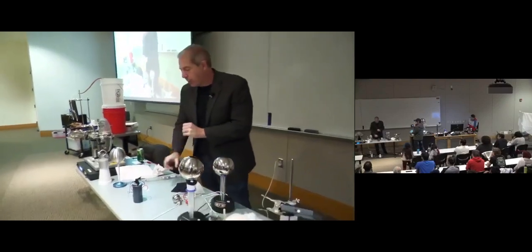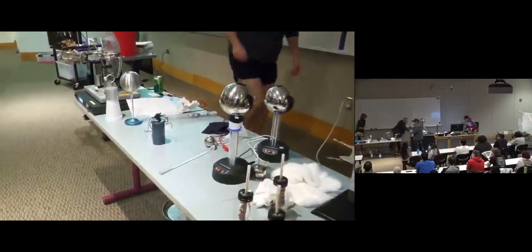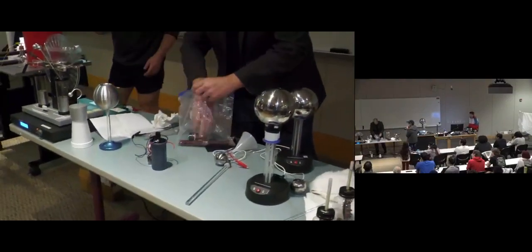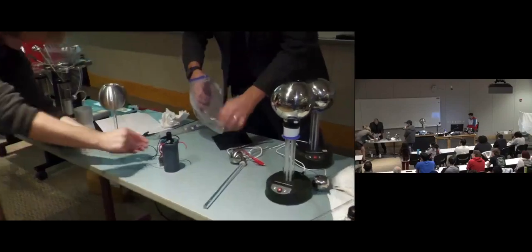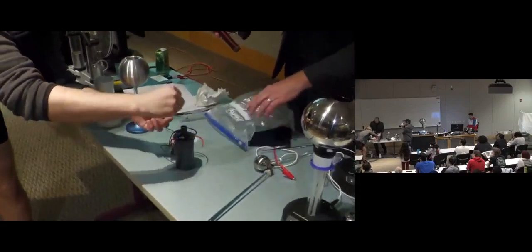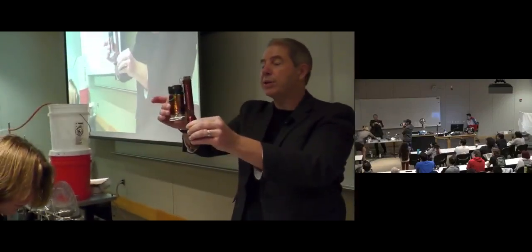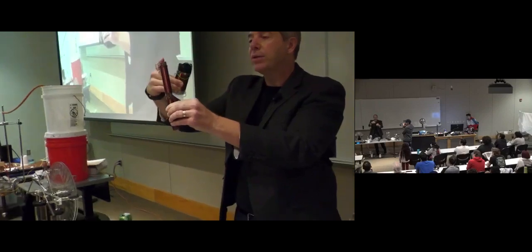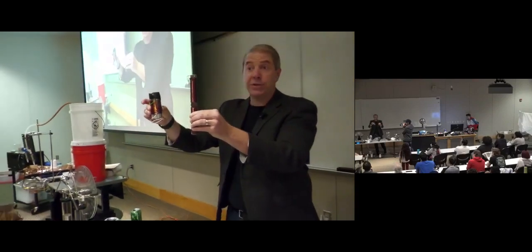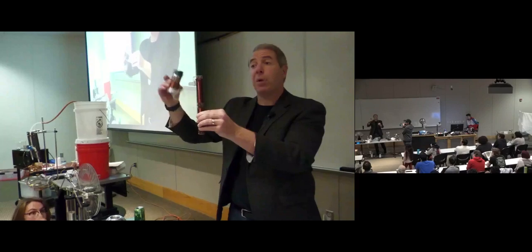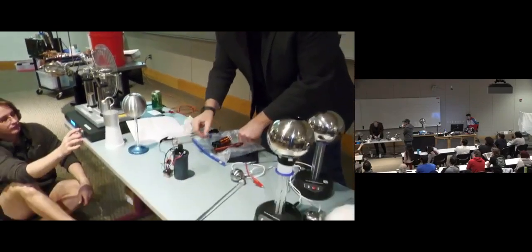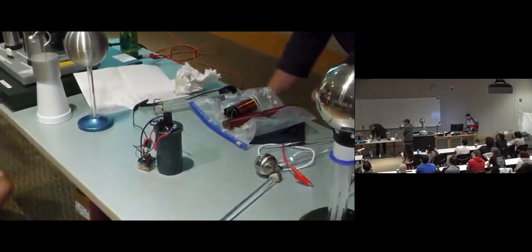What we're going to do is pass a current through a small coil. So we put current through a coil, put it next to a coil with thousands of times more turns. And when we disconnect the current through this coil, the energy has got to go somewhere. It goes into this coil, gets multiplied, and we get a huge voltage that breaks down the air. And so I'm going to demonstrate this.